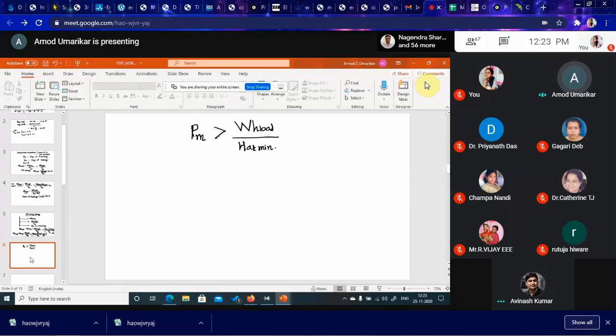It's the average kind of hours in a day, averaged over a year. This is energy and this is hours, so we'll get power. For a given PV size, because PV is available not in watt hour but in watts, we have to find out the final size in watts. So this is how we can do the example.